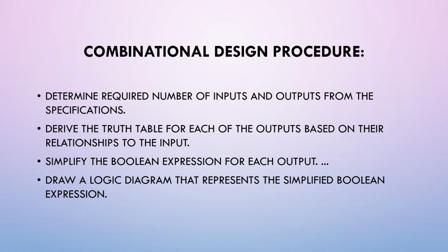Combinational design procedure. Determine the required number of inputs and outputs from the specification. Derive the truth table for each of the outputs based on their relationship to the input. Simplify the Boolean expression for each output. Draw a labeled diagram that represents the simplified Boolean expression.